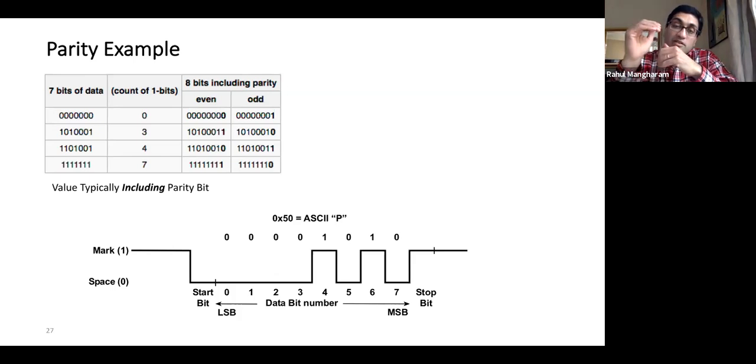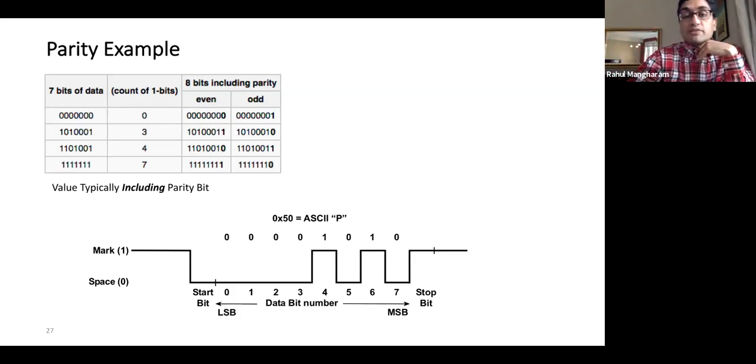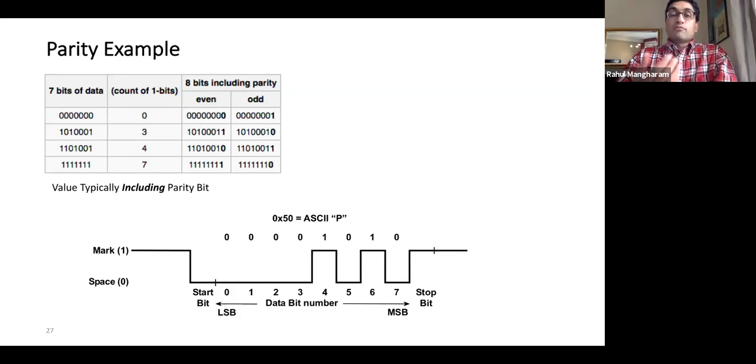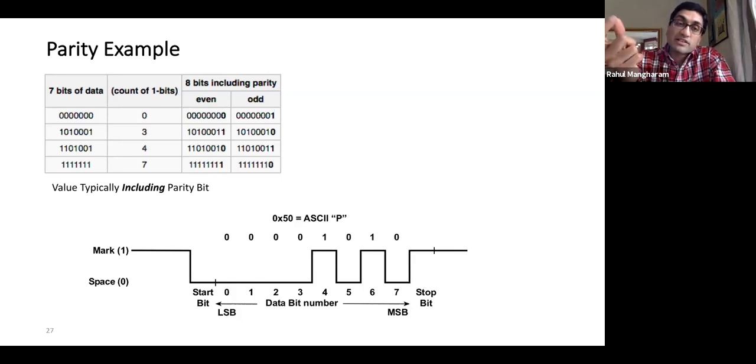So 32 bits give you a very efficient way of saying this is what you should be receiving from me. Because when you receive a message, I send you the message and I send you this extra code. What is this extra code? For a single parity bit, all that code is doing is XORing the bits and saying you should have an odd or an even number of ones. You would just receive your packet, XOR all the bits, and see whether you have odd or zero.